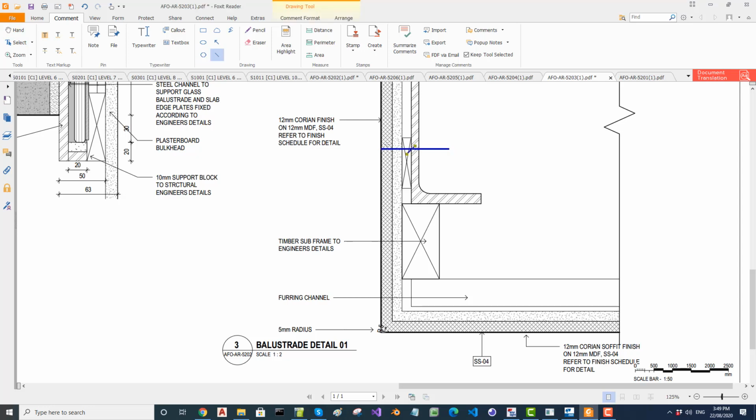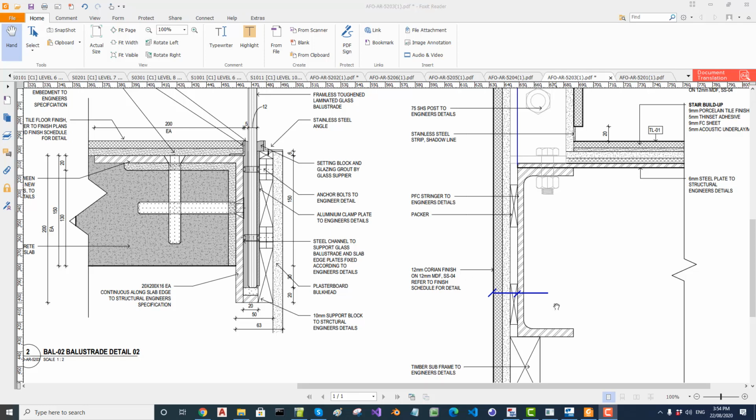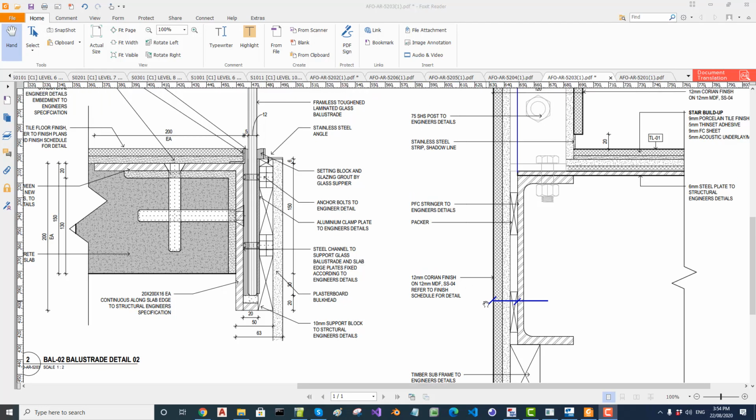That distance you got to find out from the plan view or from the drawings. You really got to find out what that distance is. Here I am actually going to scale it, which should not be done like that. You have to use the plan view, the wall set out, the center line set out, and find out what that distance should be. I'm going to scale it anyway here.